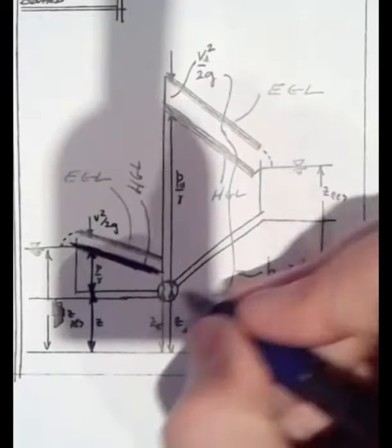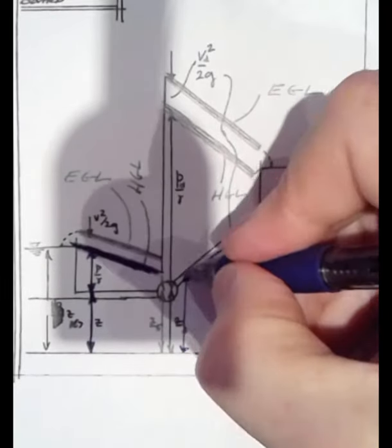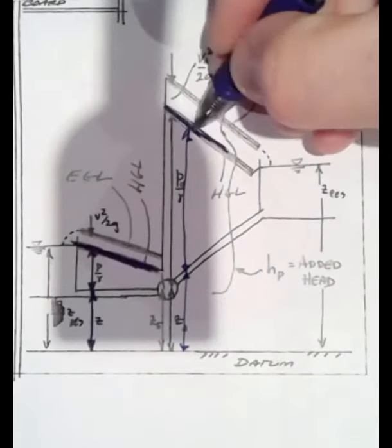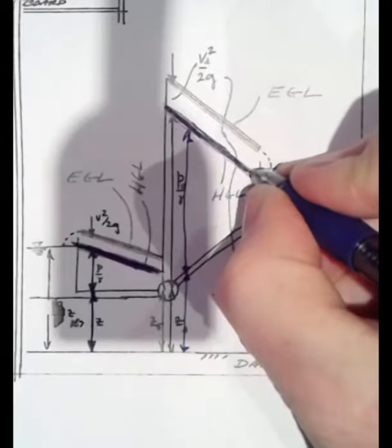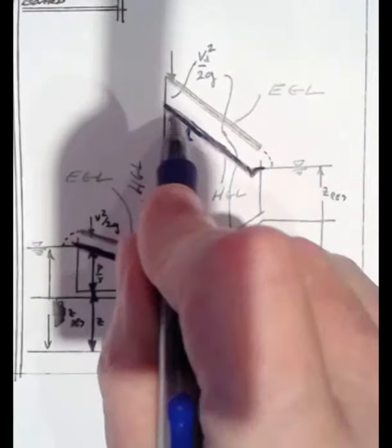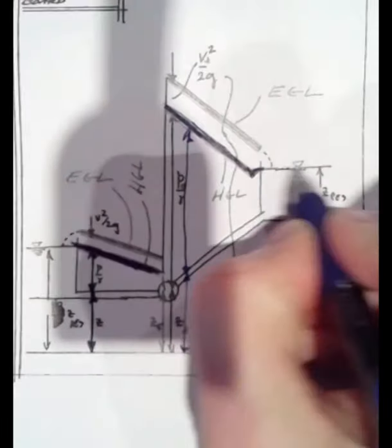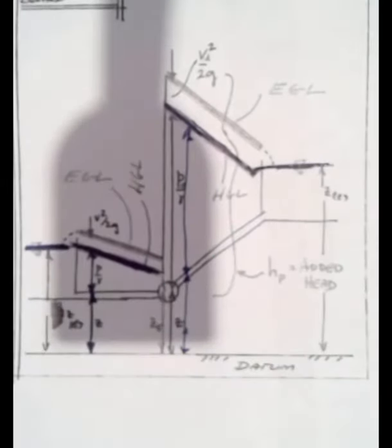And the uphill part, there's the elevation, there's the pressure, and so it would do something like that. And it might have a little curvature right there at the reservoir. Probably actually comes in above that, but that's good enough. And when we get out to the reservoir, there's the hydraulic grade line there.